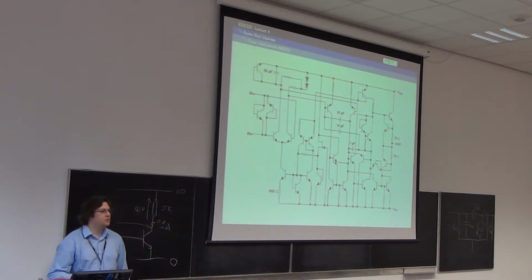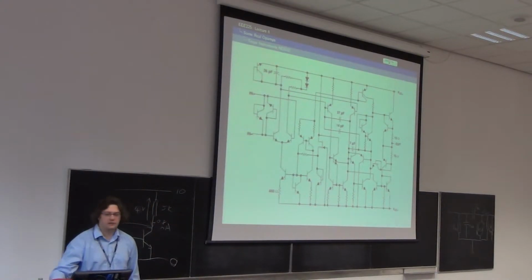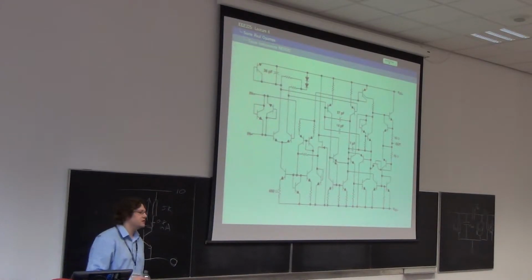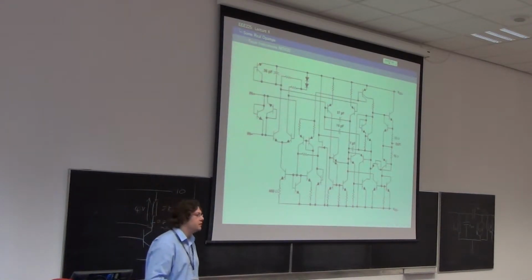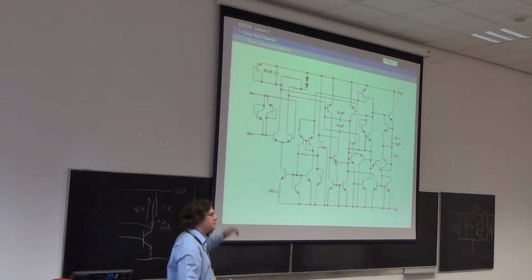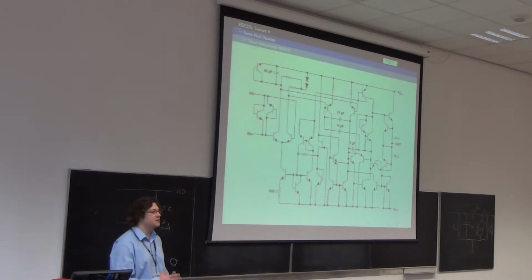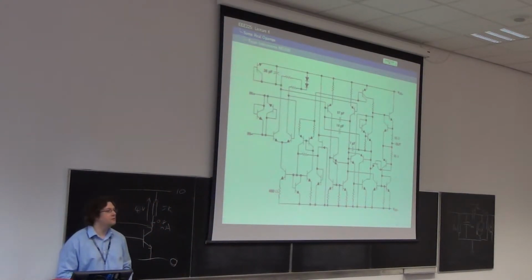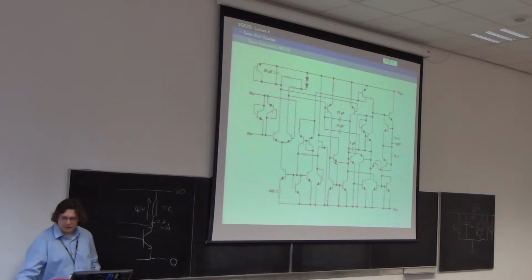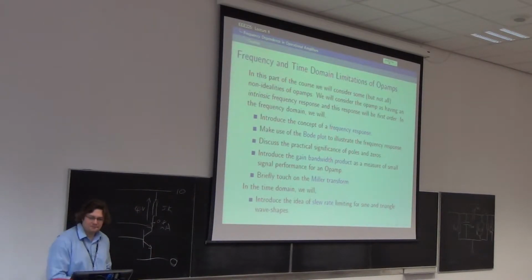It provides voltage gain, just like a Darlington does. The fact that it's differential doesn't really matter. We've got a differential output from our differential amplifier anyway, so there's no reason not to use both halves if you want to. That's all I'm going to say about that one.